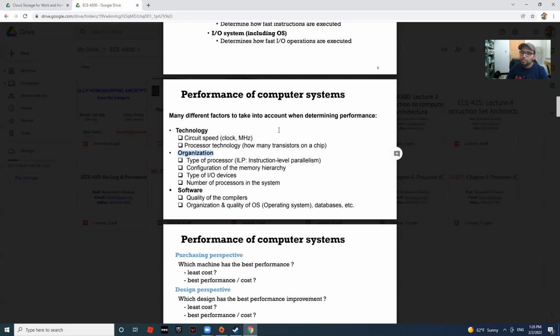Like, for instance, some of the astrophysics algorithms running on supercomputers, like the Oak Ridge National Lab supercomputers in Tennessee. Those guys have parallel machines and they call them data flow machines. And of course, that shows you high-end architectures, like ILP, MIMD, and SIMD. ILP means instruction level parallelism. Is there a possibility for one instruction to be broken into parts and each part run in parallel? That's a type of processor architecture.